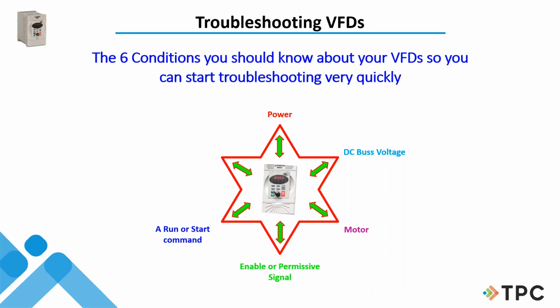It could be a push button, or it could be something on your production line that's actually going to tell it to start. I don't know where all that stuff is, because when it doesn't start, where am I going to look? And I need to know, because a lot of building automation systems tell drives to start. There are air fans and stuff in buildings. I should know, if I'm on a building automation, what rack, where it's at, and what output on that rack tells my drive to go. I shouldn't have to wonder what it is, and I shouldn't have to take the time to look it up. I should know it. So this is more information that's in your book.